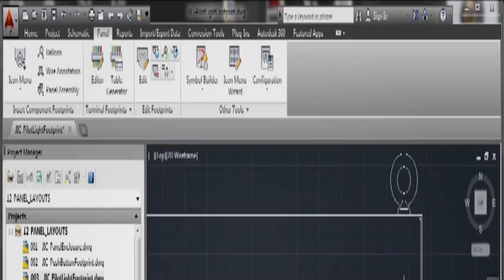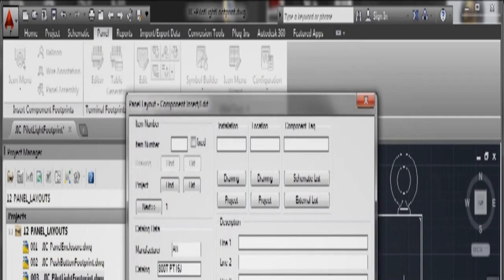What I'm going to do, I'm going to put snap and grid on, and you'll notice now I can snap to the grid. I want to place these pilot lights exactly on the grid, so I'm going to put one there. Select rotation, rotation's fine, I'll press enter to accept, and I'll do an OK repeat. But before I do that, make sure you put pilot light in the description. Always a good thing to do, then people know what it is.